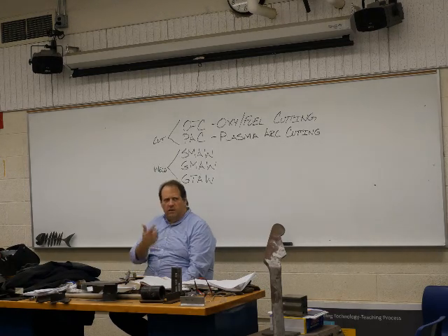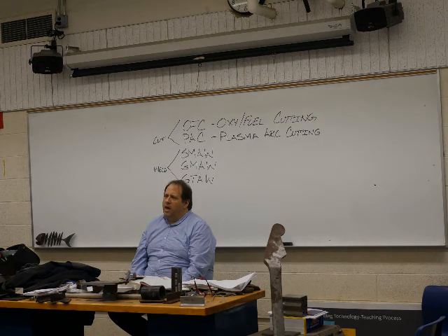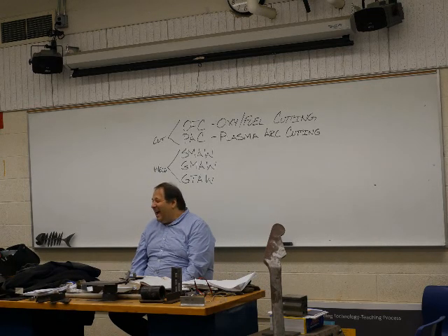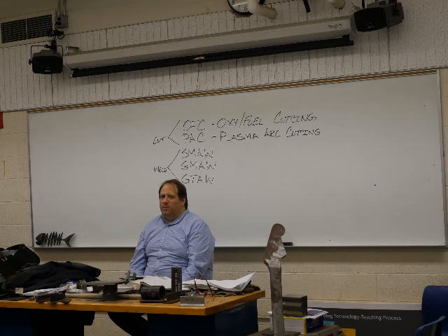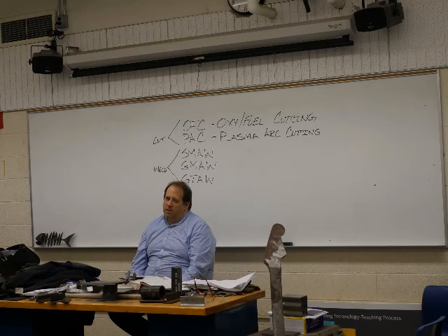Yep. Like our hand system back there is a military spec ESAB that, if you look at their specs, says that you can go up to 7/8 thick. I've done 1/2 inch. I might be able to pull off 3/4, but I'm not sure. Our system on the CNC plasma table says I can go up to 1.5 inches. That one's a pretty beefy system. I would say probably the max is going to be maybe 1 inch, maybe a little bit more than 1 inch. But that's really thick for a plasma.